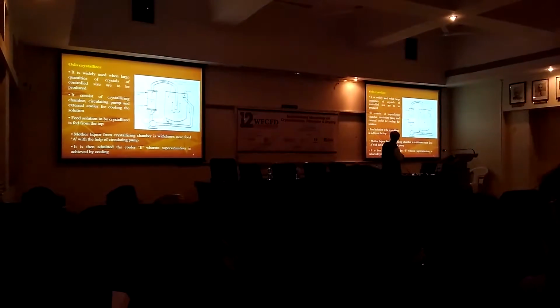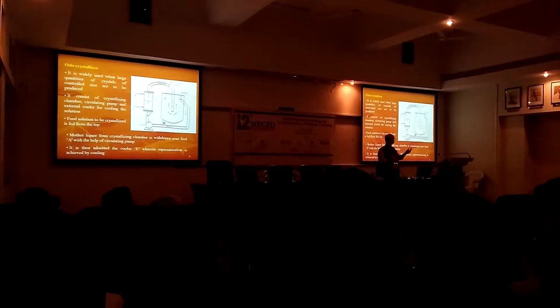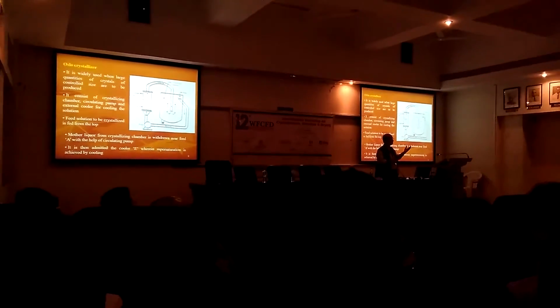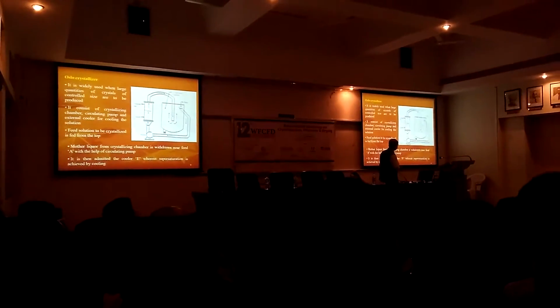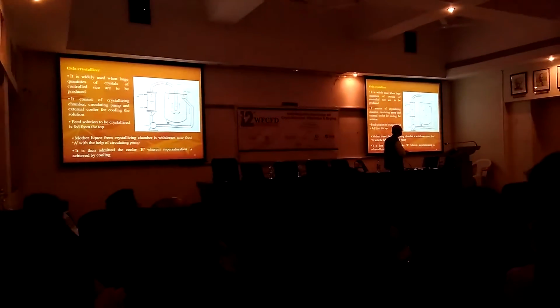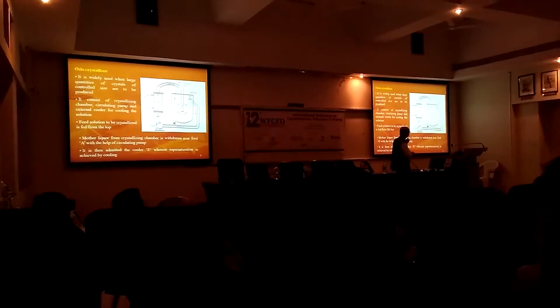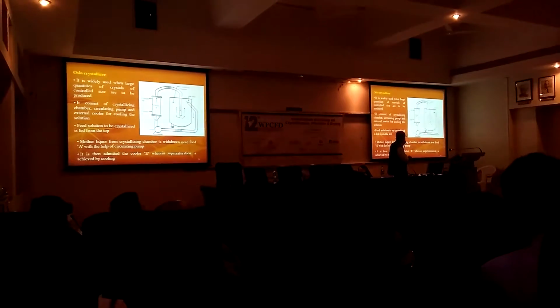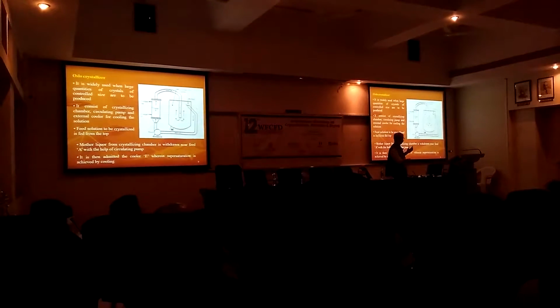The third type is essentially an Oslo type of crystallizer. This is also called an ideal classified bed crystallizer. What happens is, you take the material from in here, and then you pass it through a cooler, a heat exchanger. You take out the heat associated with it, so you create the degree of supersaturation, and this material is then reintroduced, creating a liquid flow pattern.